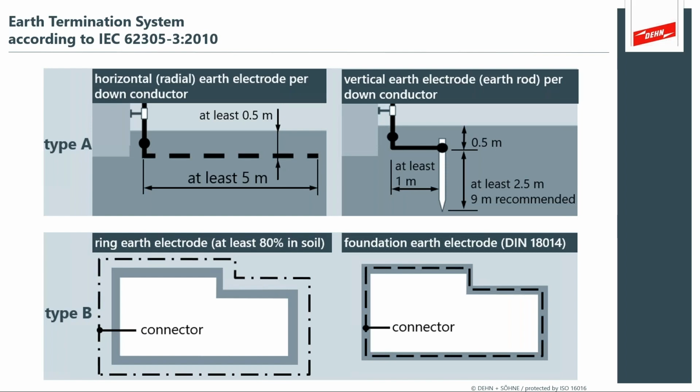What we'd like to present as baseline information are the IEC methods, and of course the NFPA methods and the National Electric Code. They do recognize two basic fundamental types: where you have what looks like a single earth rod into the soil, which would be considered type A, or type B, which is more like what you think of as a ring or a grid, a ring around the system.